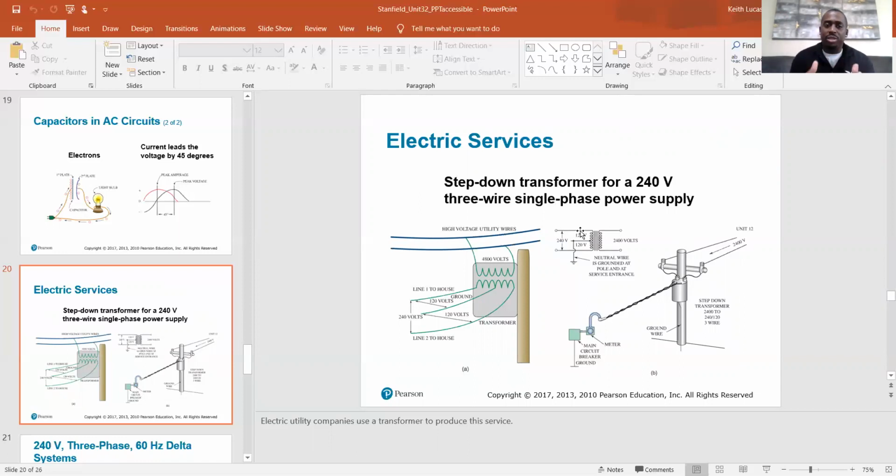So that 24 volts, where does that come from? We have a 120 volt system. Where are we getting these? What's powering all this 24 volt stuff? Well, that's where your transformer comes into play. So your primary side, which is this side, you're getting your 120 that's coming into your unit to power up your unit, you're going to take that same 120 and you're going to step it down to 24 volts. So all your relay coils and contactor coils are all going to get its 24 volts straight out of the secondary side of your transformer. That's what's called your control voltage.